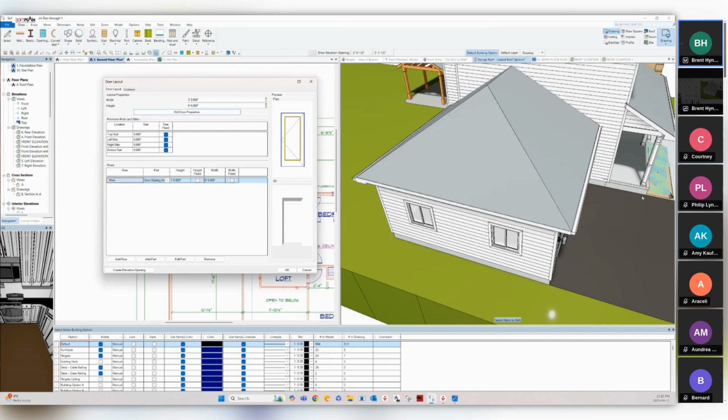All right. So what we're going to do is come in here, and I'm going to change this height to 18 inches. And I'm going to give it a fixed height. Okay, so by making it fixed, it goes up. If I don't click the fixed option, it doesn't matter what this number is, as long as it's got the space to fill in between the bottom and the top rail, it's going to stretch to that size. Okay, so I'm going to make that fixed.